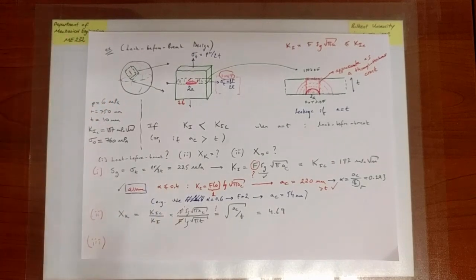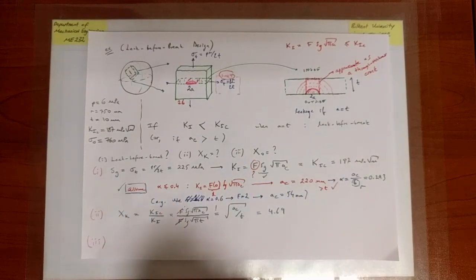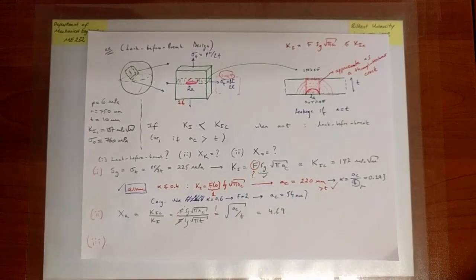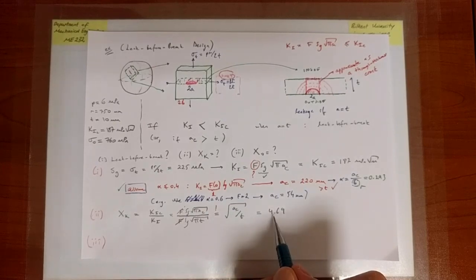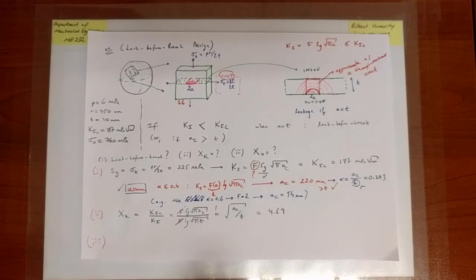Now let's go to the third part. So we are just wondering what kind of an issue this pressure vessel has. We know that it will leak before break, but it might also yield, and I may not want yielding to occur either. So the question is, the crack will start growing, and at some point it might leak. It certainly will not fracture, but at the point of leakage, there is a certain safety factor on fracture, but perhaps it will yield before it even leaks, right? And I may not want that to happen either.